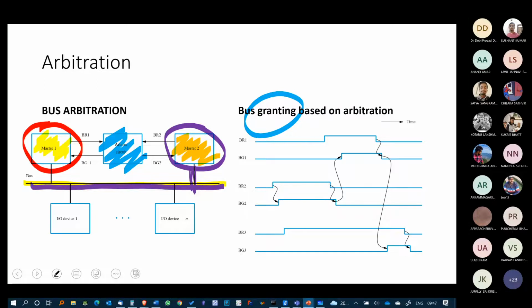So in a storytelling mode, what it means is that you lock yourself into the house. Lock yourself means you do not make yourself available outside the house. You stay inside your house. So the CPU can actually lock its doors, right? This master one can lock its doors by putting a high impedance state on its bus from inside. Then it looks as if it is not visible any longer. So that's the physical way in which the locking out happens.